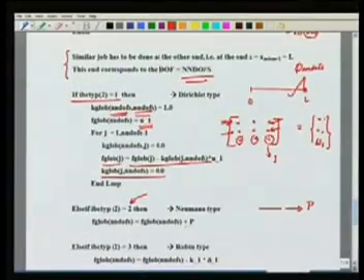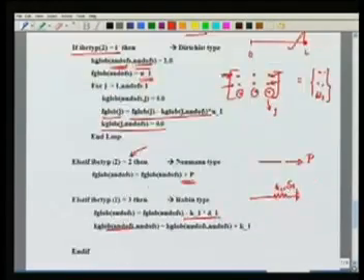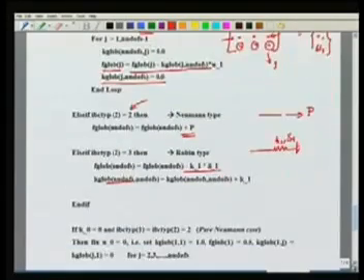Similarly, if I have to apply the Neumann boundary condition at this end, there is an end load P acting here, then that load has to be directly added to the last entry in the load vector, that is all. If I have a mixed condition here, so here I have a spring, I call it with stiffness K1 and an initial compression delta 1, then the global load vector gets modified by minus K1 into delta 1, and the global stiffness matrix corresponding to this last column and the last row, that is the last diagonal entry, gets modified by K1. So this is all we have to do as far as applying these boundary conditions is concerned. One more thing we have to check.